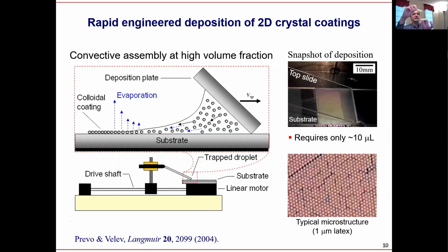Now, there is an engineering trick here. If you try to very tightly fix the slide like that, and then try to drag it very precisely yourself, you cannot do that, right? With such a very thin meniscus, there is always going to be some misalignment, so the whole thing becomes screwed up very easily. The simplest way is actually to have a flexible link here. Then when you put that slide, it just resides on top of the other one, self-aligns, and drags along the top of the bottom slide.